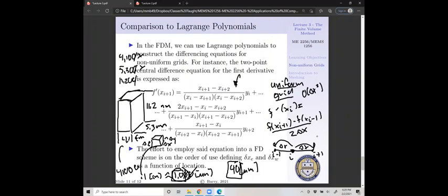You're going to have some variation. Now, it might be uniformly spaced throughout your domain, but as we're going to see in our 2D solver and 3D solver of our finite volume formulation, even if we have different aspect ratios, we have to take that into account. So you are going to have to populate your delta x east, delta x west, delta x north, delta x south, delta x forward, delta x backward, and populate those as different values, which then update your coefficients that then get taken into account when you solve your matrix.